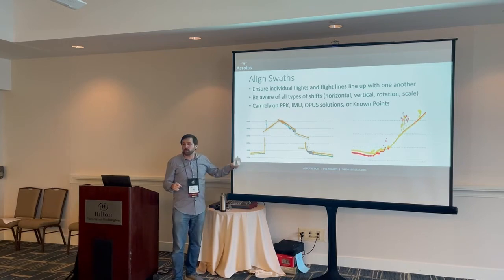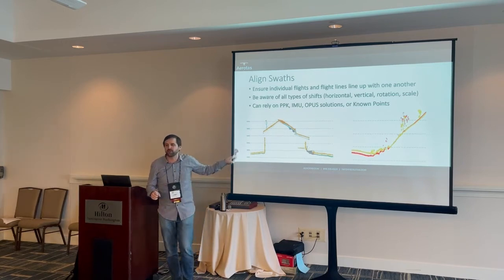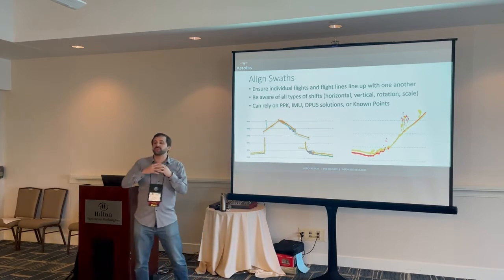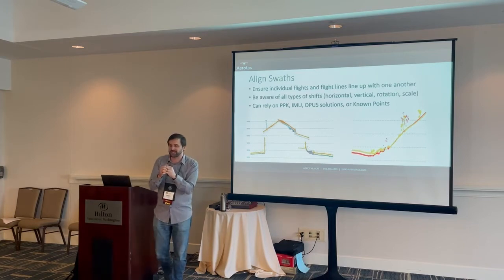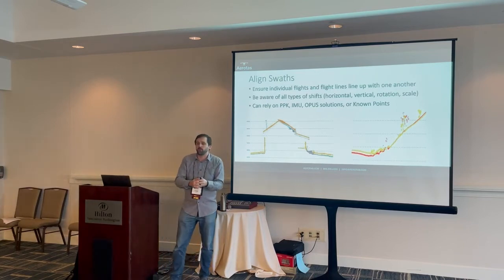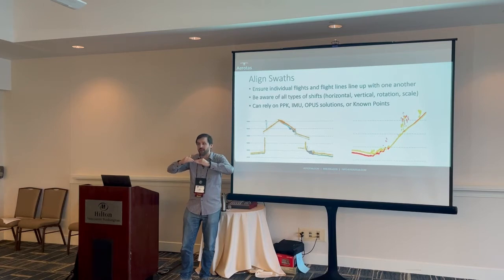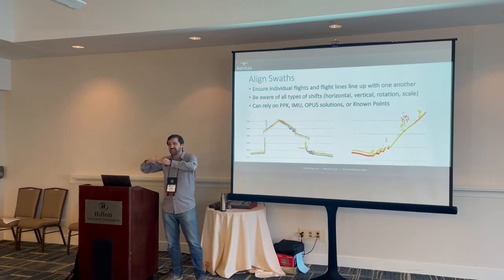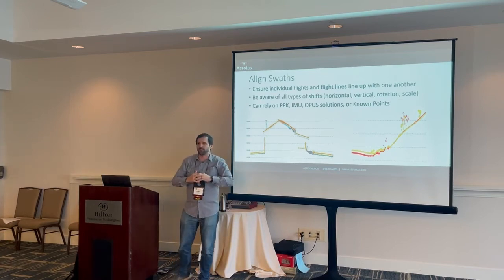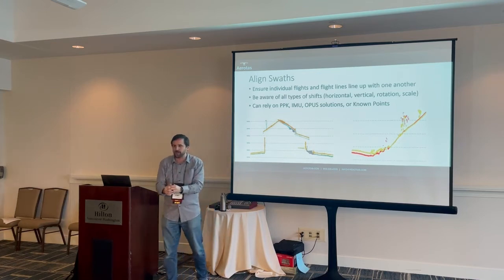It's still, at this point, you're not looking for accuracy yet, you're looking for precision. You're getting all of these to line up so that they are internally consistent with one another, and then once you have that single block that you know is precise, then you bring that whole block to your ground control points to make it accurate.